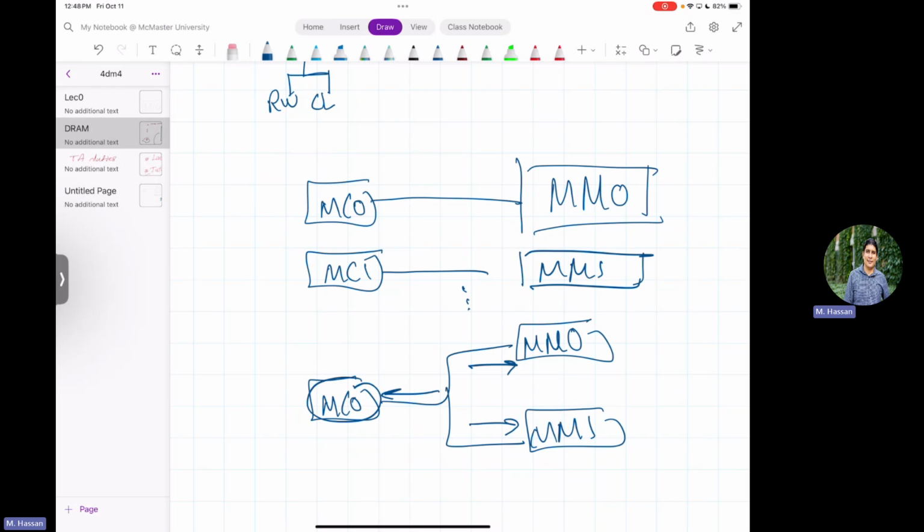Yeah, true, much more parallelism. In your desktops, for example, if you have ever assembled a desktop, you will find multiple slots for your DIMMs. But at the end, you don't really have as many memory controllers on a chip as the number of DIMMs you have. In most of the advanced Intel chips, you might have two memory controllers, so one memory controller will be managing more than one DIMM channel. You see what I mean? So there are still some serialization points. They're not completely independent.